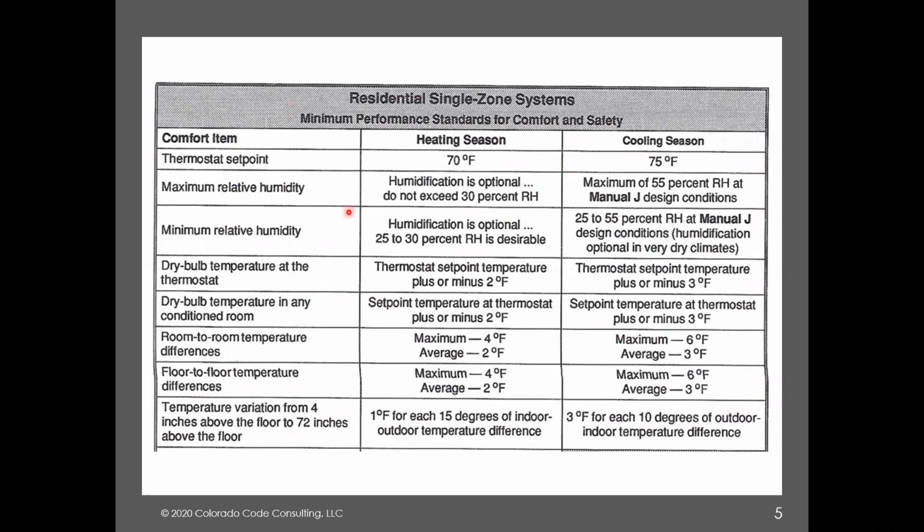So the idea here is it's saying, okay, well, during the heating season, what are the expectations based on humidity or thermostats or room to room or floor to floor temperatures? And we had a few examples of that where during the cooling season, if it's a design day at 90 degrees, say there in Colorado, you might expect up to 6 degrees between the first and the second floor.